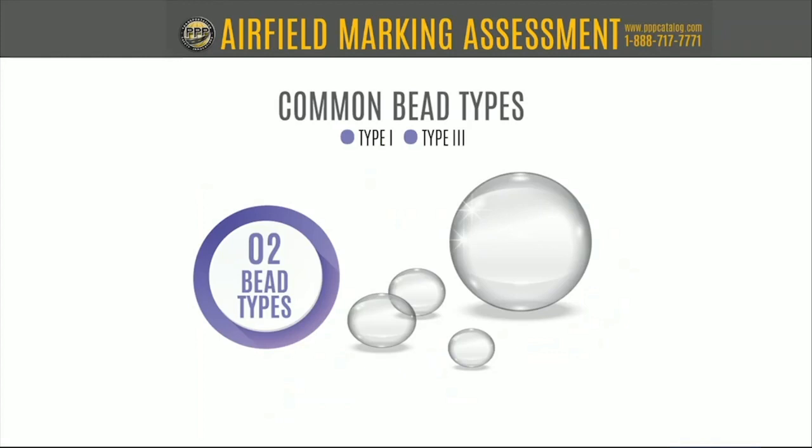So you have superior wet visibility with a type 3 bead. And I want to be careful because we're using a general term here saying type 3, but the actual spec is TTB1325D type 3 high index reflective glass beads. So these are high index beads, which is a little different. There are some type 3 drop-in beads out there that are not high index beads. And that's what's giving you that ability to see through or get that retroreflectivity under wet conditions and so forth.